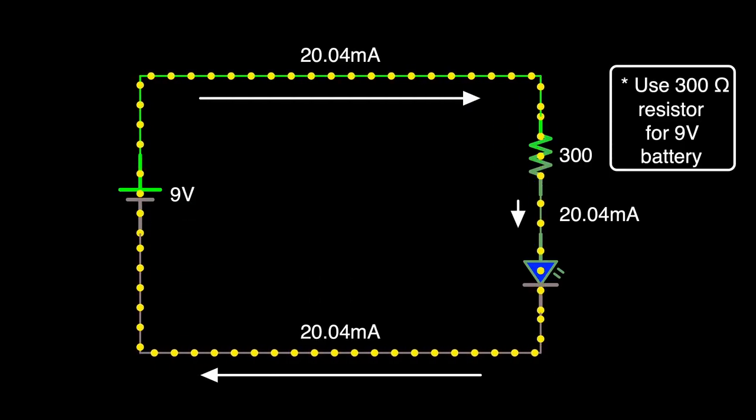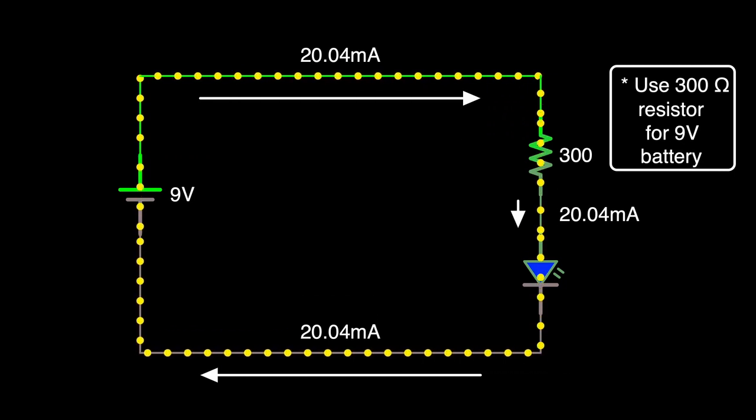Now is a great time to talk about how voltage and current change when flowing through both of these types of circuits. Let's talk about series first. Since we're talking about your LED and resistor circuit, Emma, what color of LED is your favorite? Blue. Okay, imagine you have a battery, a blue LED, and a 50 ohm resistor all connected in series. In a series circuit, the current would be the same everywhere in the circuit.